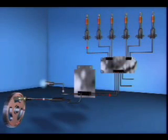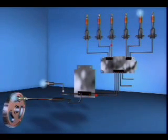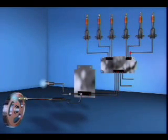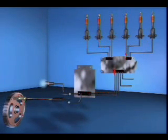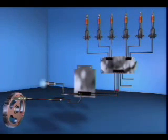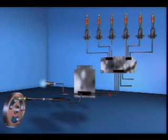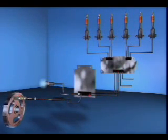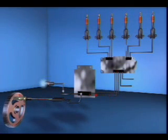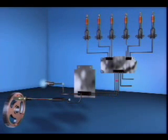The ICM has a built-in engine protection feature. The ICM monitors the high voltage pulse to cylinders number 3 and number 4 to determine if these coils are firing. Anytime the continuity of the signal wire, return wire, or primary winding for cylinder number 3 or number 4 is broken, the high voltage pulse from the ICM is prevented, and the ICM ceases the discharge to all coils. Therefore, removing the harness at the number 3 or number 4 coil, or from the ICM, shuts down the engine.